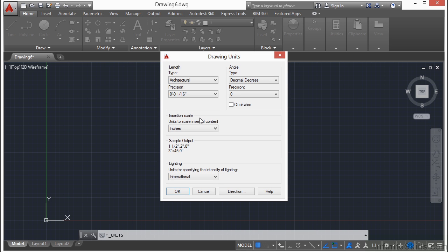It's smart enough to know that 12 inches is a foot and will display your object as being 1 foot, 0 inches long. And when you're entering objects to specific lengths for architecture, you can tell it to be 2 feet, 0 inches, or you can type in 24 inches. So keep that in mind. Architectural format will display fractions of an inch in fraction form, while the engineering setting displays them in decimals of an inch. Now, the other unit settings that we have here can be used to represent any form of measurement.